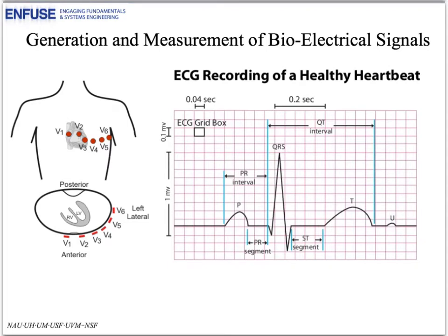In the previous slide we mentioned briefly the GSR, or the galvanic skin response, and in that case a small current is passed between 2 electrodes that are applied to the body, and the resistance, or 1 over the conductance, is determined by measuring the voltage drop. In the case of the ECG, the electrodes are applied near the heart, and we're actually measuring voltages that are being generated due to chemical processes within the body.